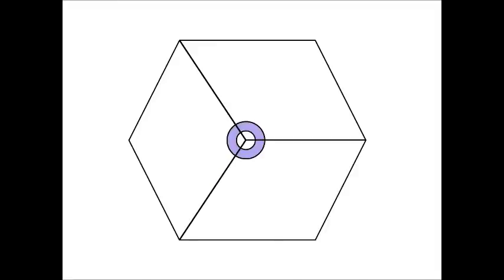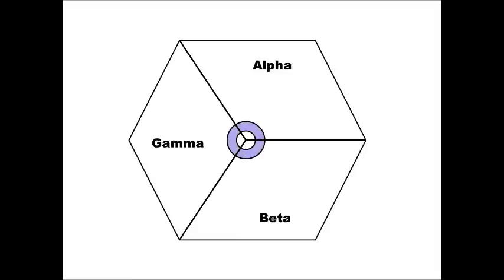Here, the base station contains three antennas facing in particular directions. That means instead of radiating in all directions, it radiates in one particular direction. Thus, directivity increases. These sectors are known as alpha sector, beta sector, and gamma sector.